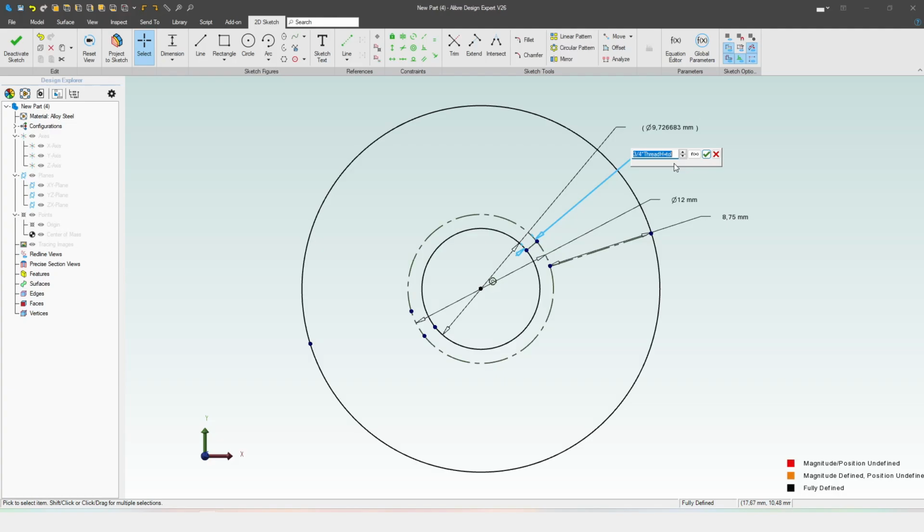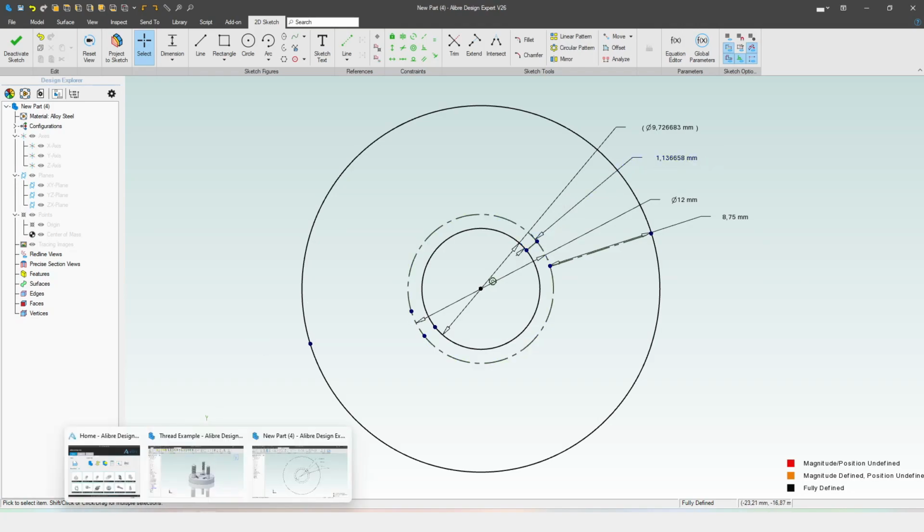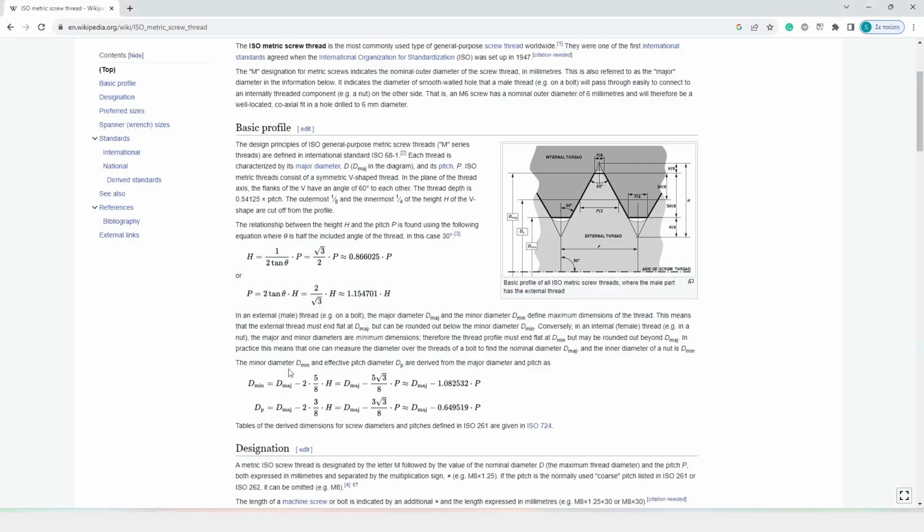Yeah, no, it makes sense. It's 3/4 of the thread height plus a tolerance if you want to have an even smaller minor diameter. Obviously, if you use a negative tolerance, the minor diameter will be larger, and so on, right? So how did we arrive at this?